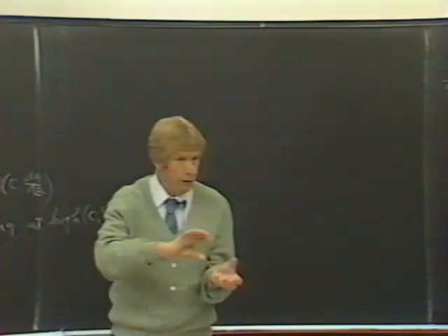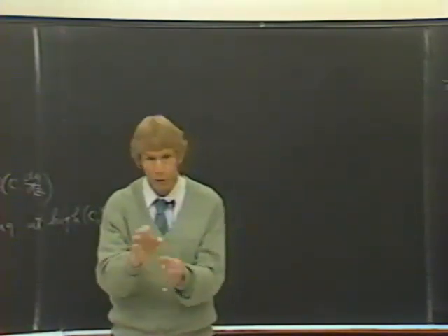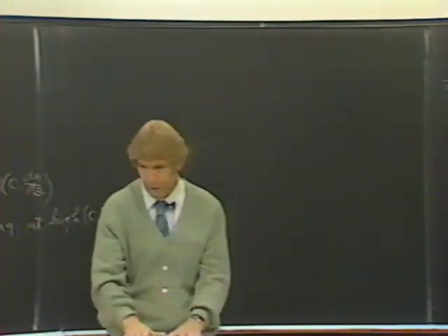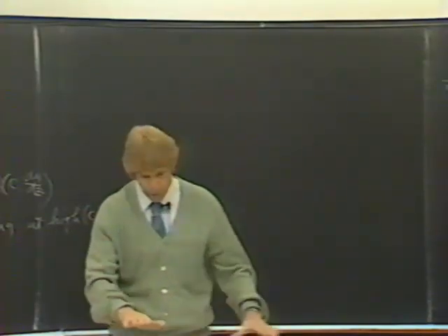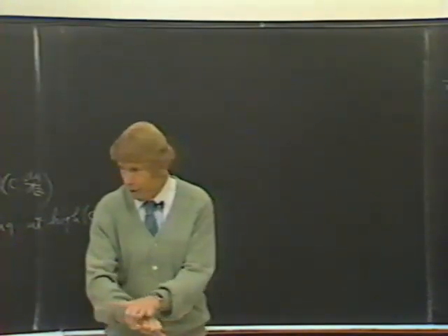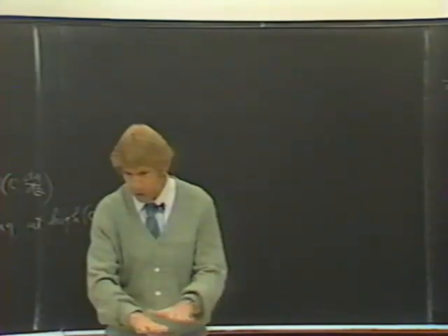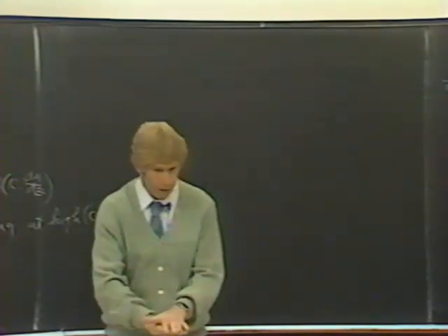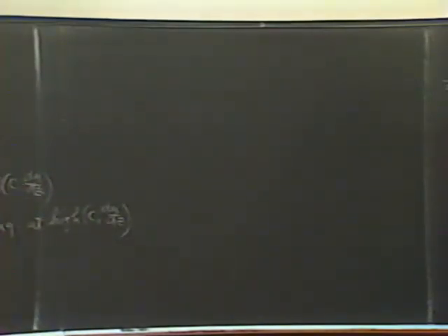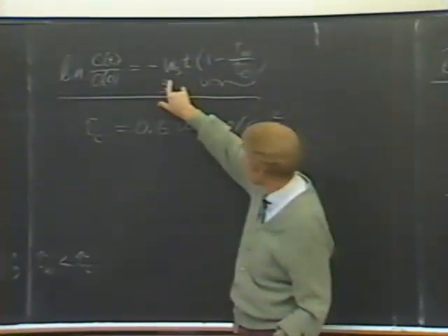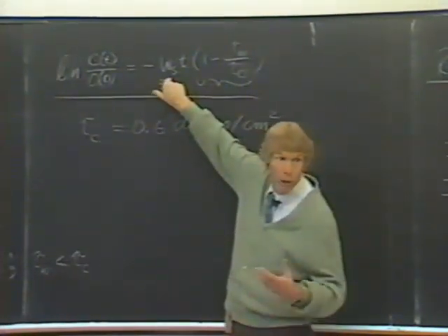So our picture here is that we have a settling velocity that's a function of concentration, which determines the frequency of collision in the bed and above, or near the bed and in the waters above, and the velocity gradients near the bed. It breaks up at high velocity gradient and reaggregates during lower velocity gradient. Then we already talked about the hindered settling and frequent no settling.